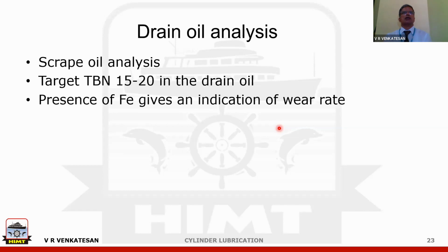Some vessels have liner temperature monitoring. When you have sailed on ships with that, the temperature of the liner is also being monitored to keep track of how it is. Then yesterday, one of the students also asked about load-dependent liner cooling. That at low loads, you keep the liner at a higher temperature to reduce corrosive wear. So, in short,